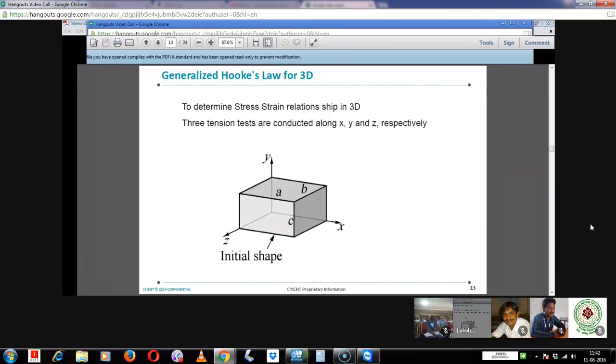Whether we need to do 360 degrees or 2D is sufficient. For this complex geometry, can we do 2D analysis? Can we do a single sector model? So there are three options here: 360, 2D, and sector. So which one do we need to choose? This is very important.